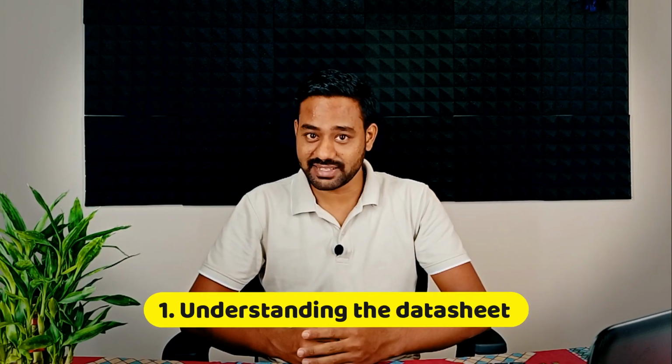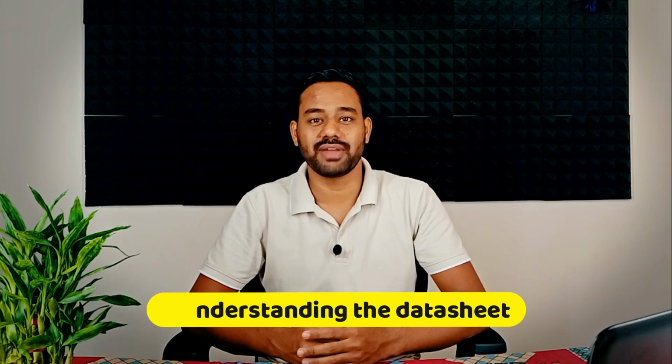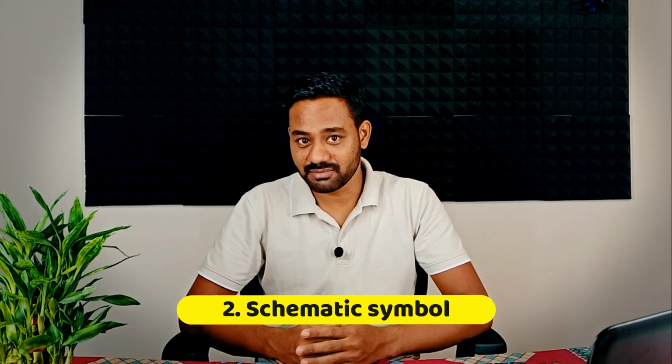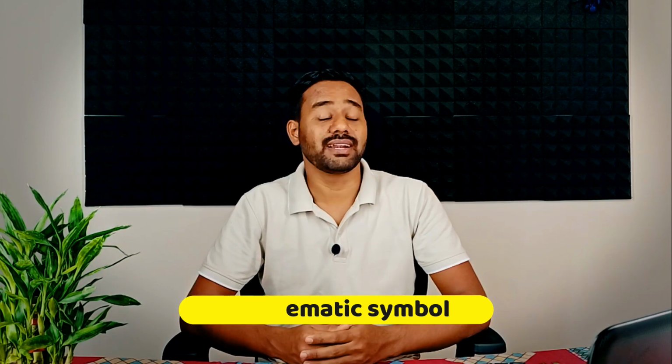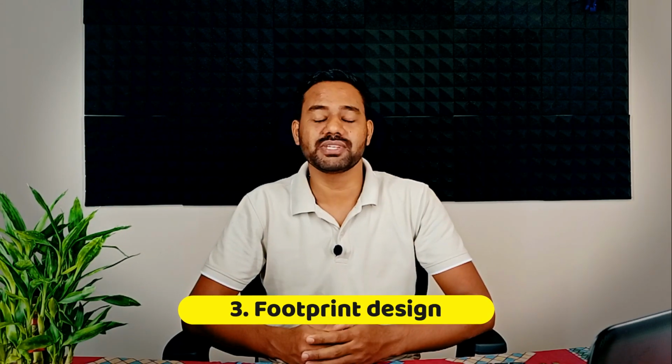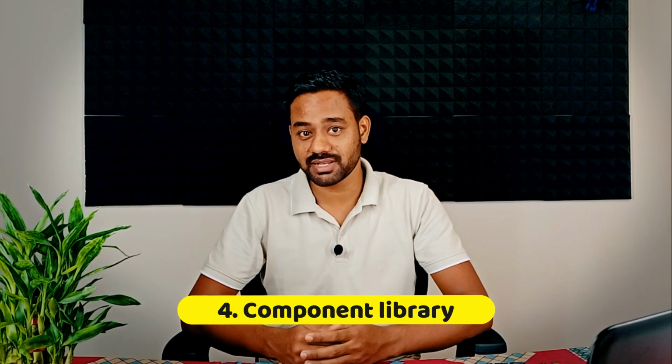As always, this video is divided into 4 important parts. First is understanding the datasheet by going through the datasheet of LM2596. Second is creating a schematic symbol using the IEEE standards and understanding how to design it according to the user perspective. Third is creating a PCB footprint using the IPC standards and Cartesian geometry. Last but not least, the fourth step is creating a component library by combining the schematic symbol and PCB footprint that we just created.